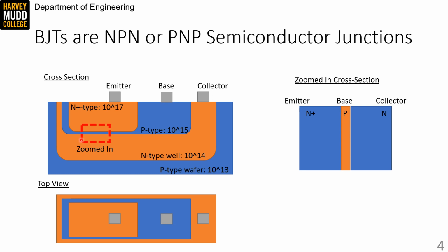You can see a top view of this transistor on the bottom of the slide, which is the kind of view that you would see as a circuit designer. Circuit designers mostly control X and Y dimensions when making chips, while device designers have pretty exclusive purview over the Z dimension. This top view reveals there's kind of a lot of wasted space in this particular BJT because the contact is surrounded by a ton of area here, and there's dead space there, and there's dead space there.